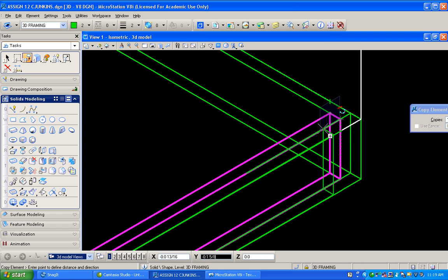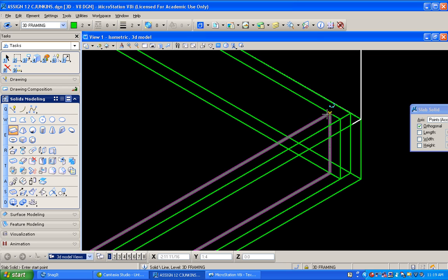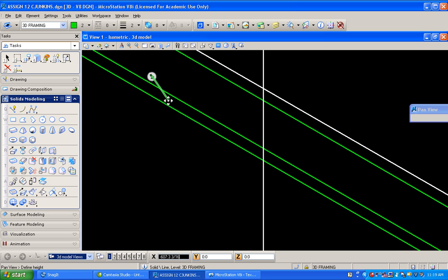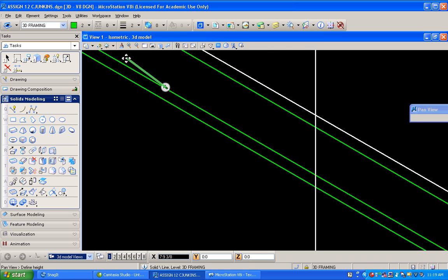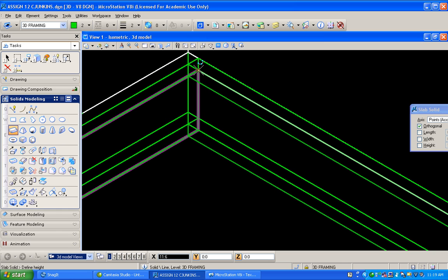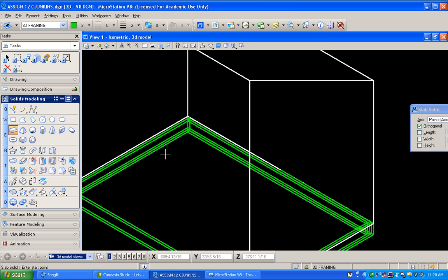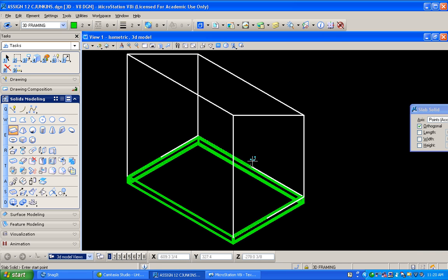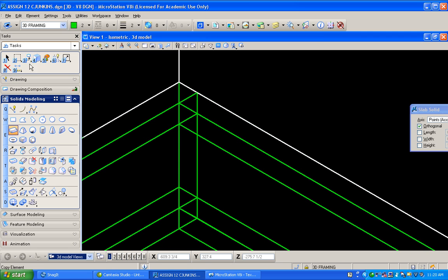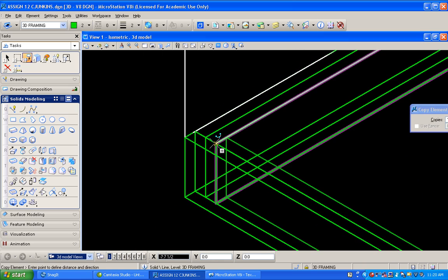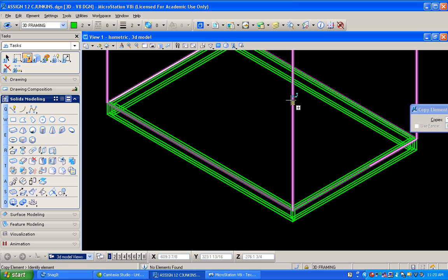We'll assume we've got all kinds of money to spend. We'll double band the whole framing all the way around. Colon 1.5. You just always want to make sure you're not overlapping the joints, that they're all butted in place. So you can see how these are staggered. I think we can just copy this one from this side to this side. So now we've got double banding all the way around.